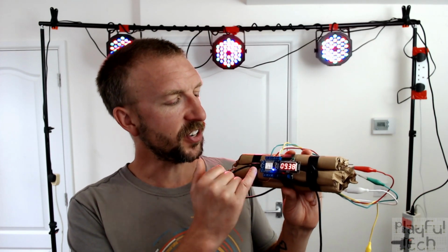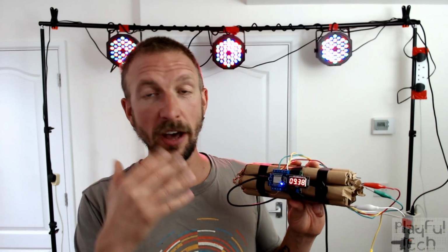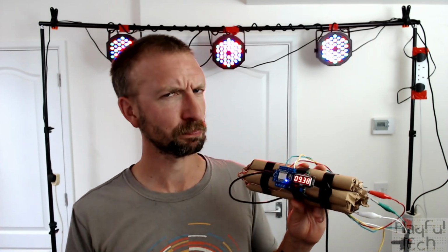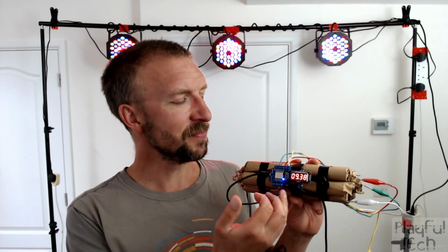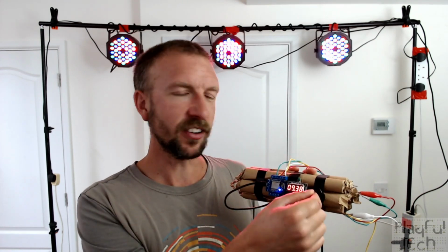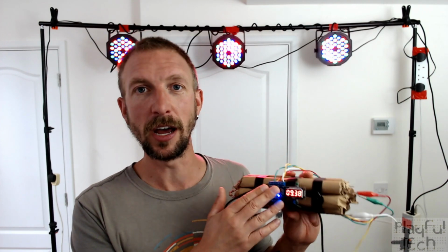The D8 pin, unlike all the others which have pull-up resistors, has a pull-down resistor. A bit strange. And certain pins like D3 and D4, you can't have them connected to ground during boot up, because if you do, the thing will fail to load.